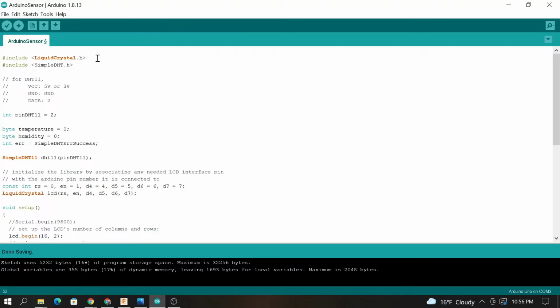Here's the problem with the AVR stuff. There isn't really a library that is going to work with AVR and an LCD right now that I know of using 16 megahertz. This chip is running at 16 megahertz and not 8 because it's on the Arduino board, which makes it very difficult to find something that is going to be compatible unless I rip the chip out of the board and put it on a breadboard, stuff like that. But I was running out of time.